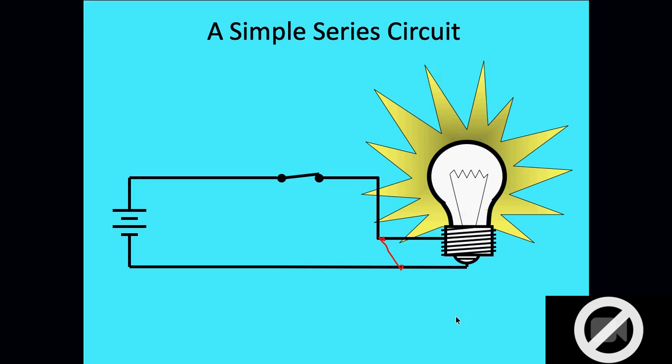So there's going to be no resistance in this circuit, right? So this becomes what we call a short circuit. A circuit without a load, or where the load is bypassed, is called a short circuit. Now, what happens when we have a short circuit? What's the outcome? Blown fuse. Yeah, you're going to blow a fuse or a breaker.